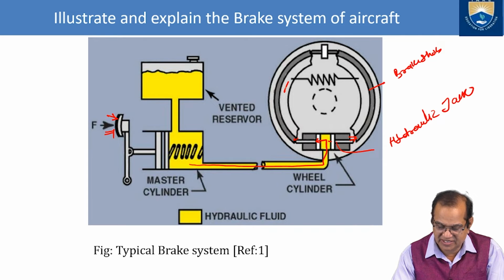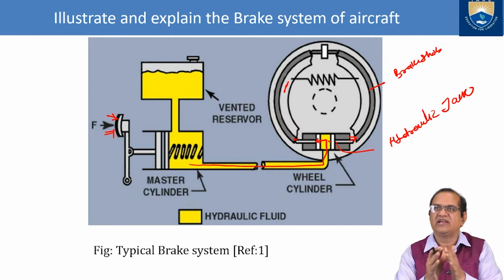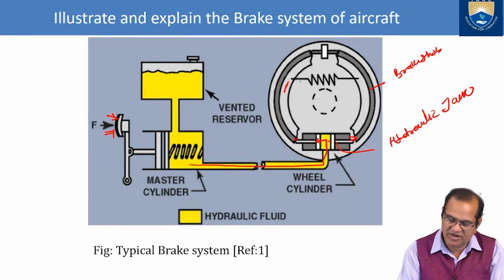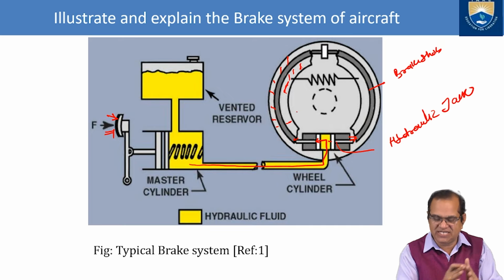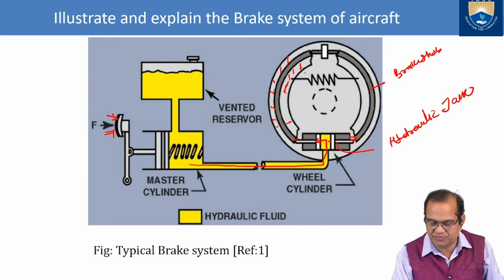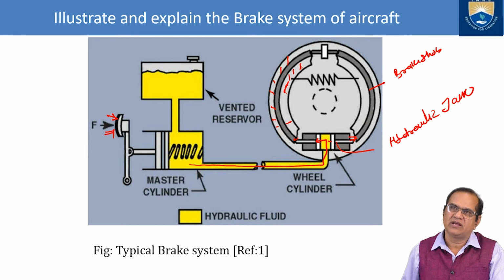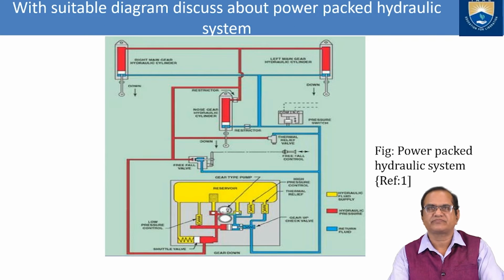And these are brake shoes, and this is operated by the spring. So as and when you release, this spring will again disengage. So brake on and off. As you apply this, the brake will be on, because these shoes will be intact. As and when you release it, pressure will be released and this spring will try to reopen. So like this, hydraulic brakes are working. Most of our vehicles, even aircraft also, use hydraulic brakes.